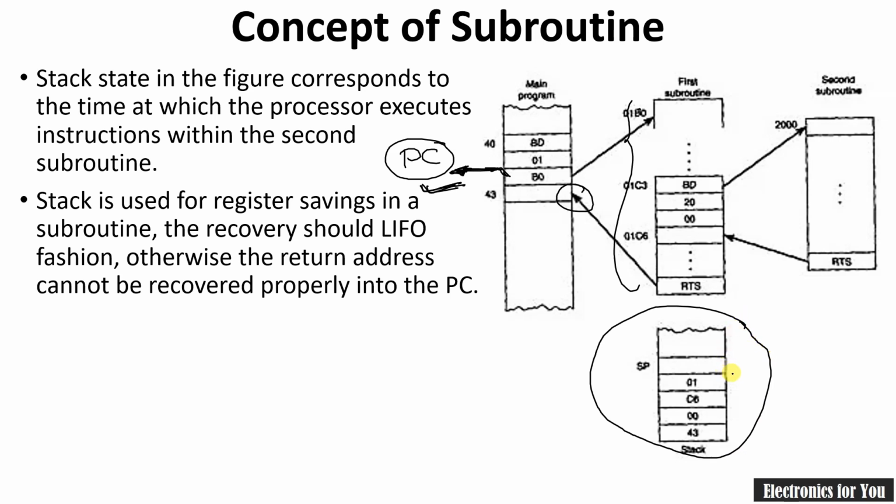Stack is nothing but internal memory, and you can see here that some address is stored, some data is stored here, and this data indicates the previous address of the program counter from before the subroutine executed. Therefore the stack is used for register saving in a subroutine.